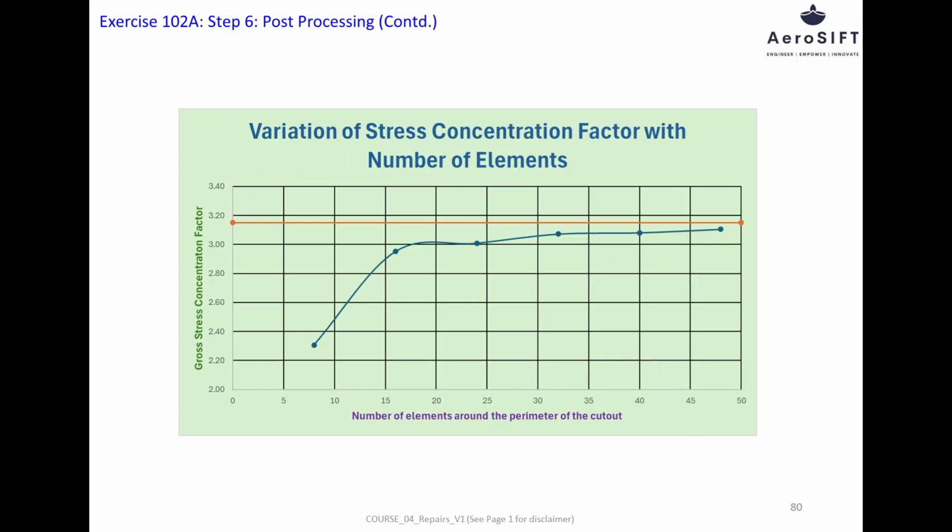This confirms that using a finer mesh near the hole leads to results that are closer to the theoretical expectation. It also visually supports the idea from the previous slide that having too few elements can significantly underestimate stress, while a sufficiently refined mesh provides reliable and accurate results.